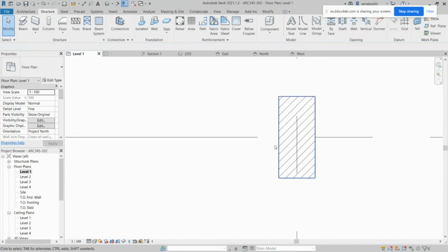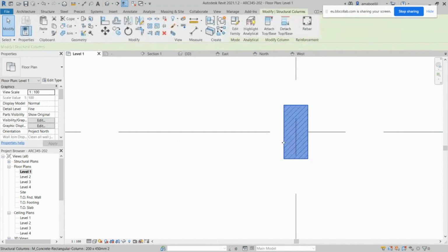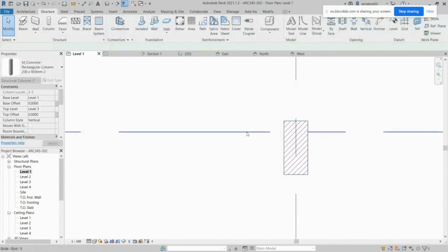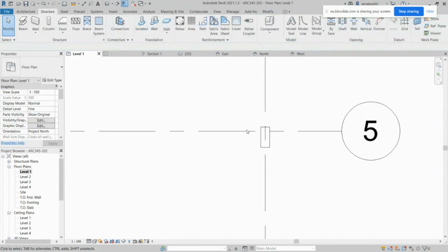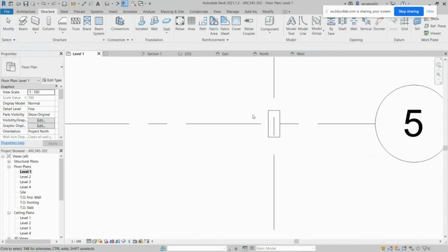What is the orientation or the relation between the column and the grid? Sometimes we said if the column is going to shrink as you go up, this should be respected with one side, so you might end up shifting it a little bit like this, so that when it goes up, one side is respected. This is the clean surface, and the column is going to shrink from that surface. We talk about this, and I hope that you understand the basics of that.